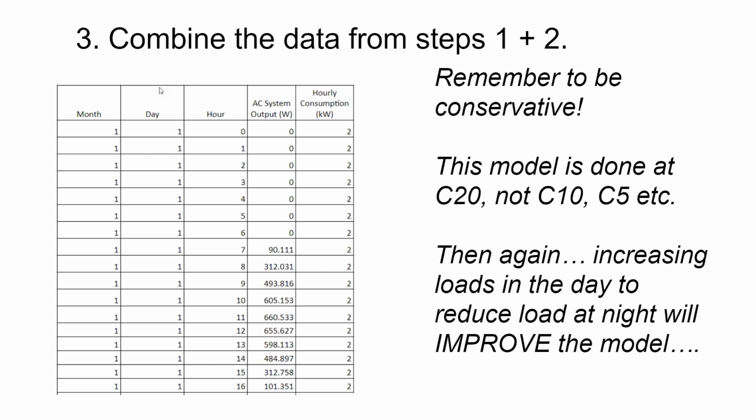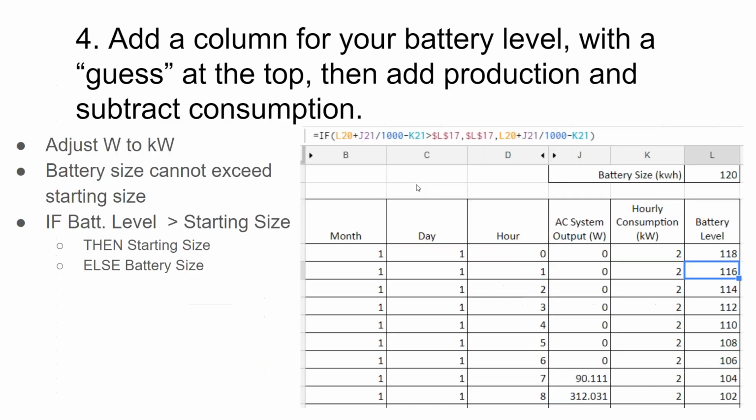In fact, most lithium ion batteries have their storage capacity rated at a 2-hour discharge rate. You try to discharge it in 1 hour and it'll store less than that. Same thing with lead acid. It'll become a little bit more clear when we look at some spec sheets.